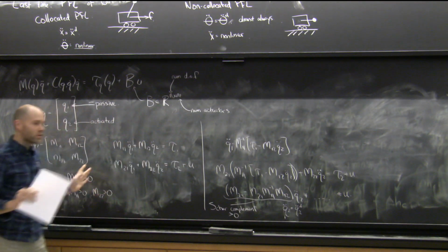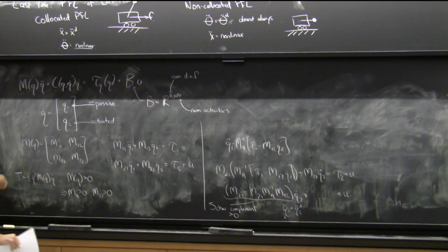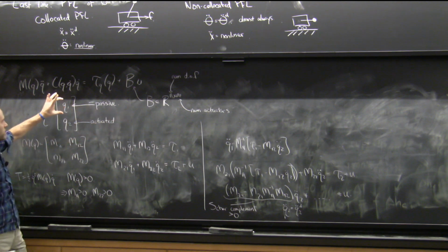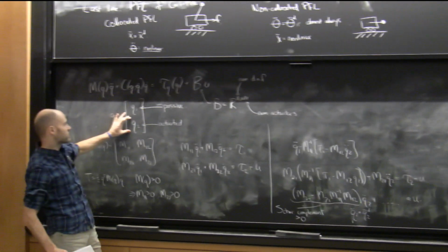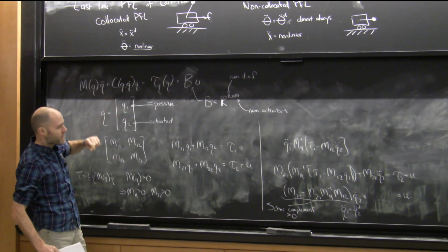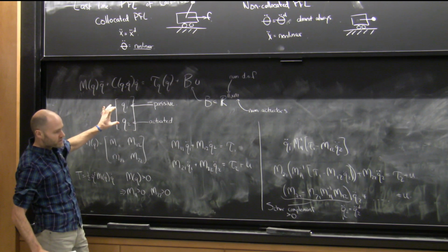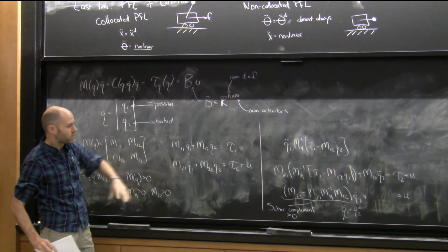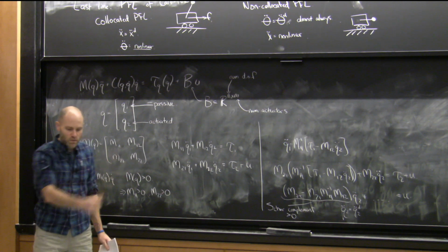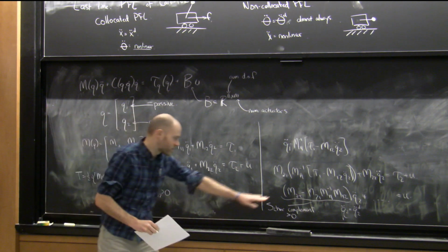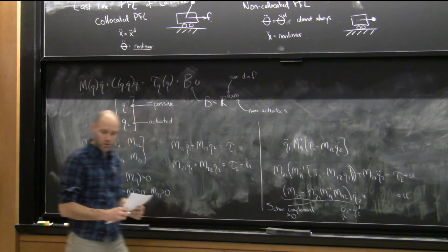Okay, so in the general form, well, pretty general, I did assume that the actuators were simply coupled, that there were motors applying directly to some joints and not the others. But up to that simplification, this is a pretty general form, and it says that always, in this form, this thing is always invertible for all Q, okay?